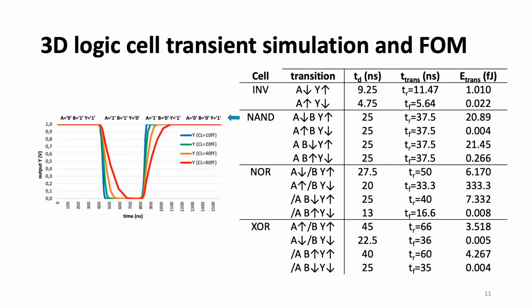This measurement protocol is compatible with library characterization necessary to enable logic synthesis of more complex functions. The figures reported here are far from being competitive with the advanced technology nodes. This was expected since the compact model parameters were calibrated on a rather large experimental device.